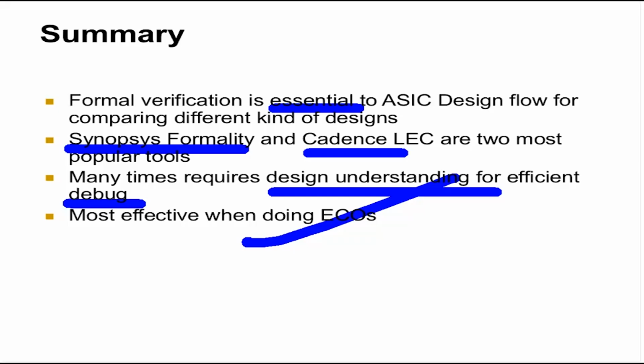But now let's say, during all this time period, functional verification will keep going on. Functional verification is never complete. The fact is that functional verification is rarely complete. Then there might be some specification change, or some new bug that you discover, and that requires an RTL change. Now what do you do? If you start from synthesis again, you will take 2 to 3 weeks to come back to the state where you are now, that is, close to sign off.